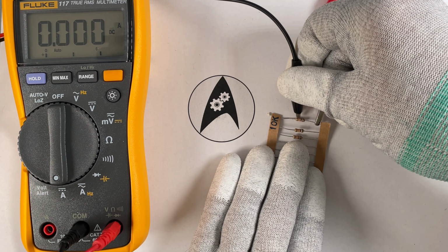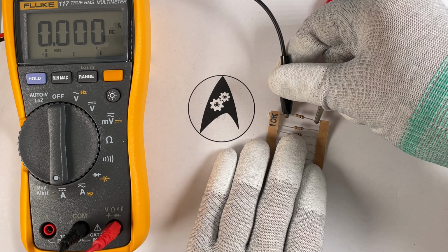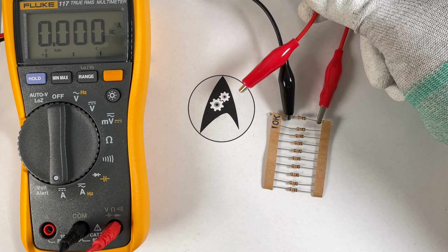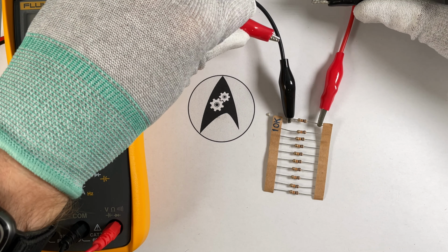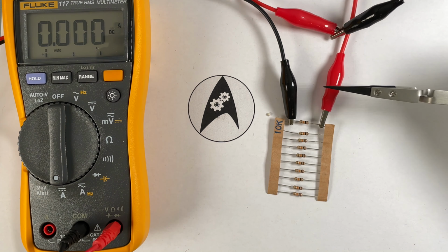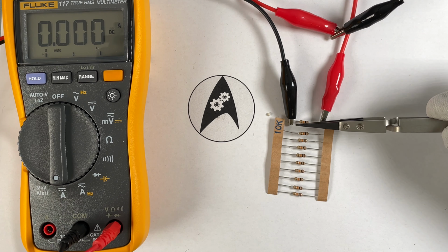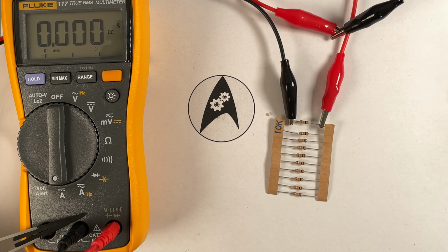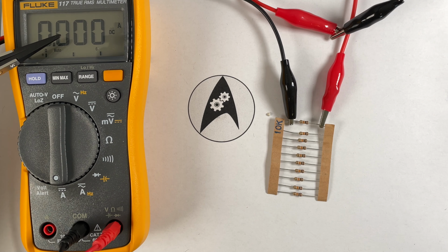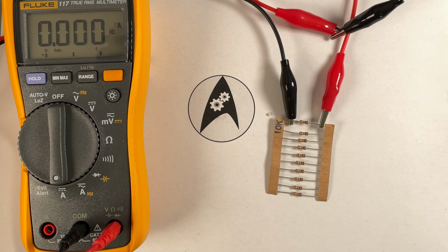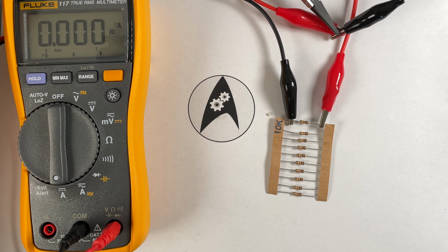Now the current flows through the amp meter, leaves the amp meter through the red cable here, and if we connect the red cable, leaving the amp meter, directly to the negative terminal of the power source, the current now enters the resistor from the right, leaves it on the left, flows through the black cable, enters the amp meter through this terminal here, displays the current flowing through it, and leaves the current meter through the red cable, which ends up here, and the black cable you can see connected to the red one leads back to the power source.